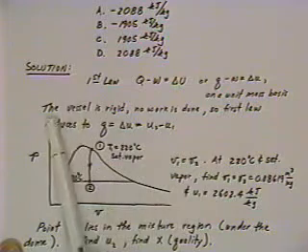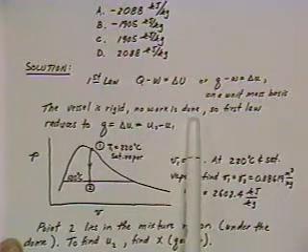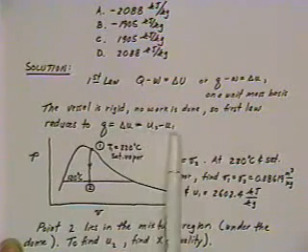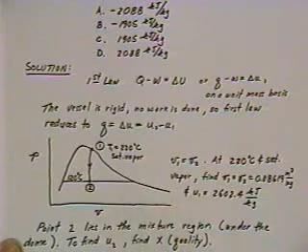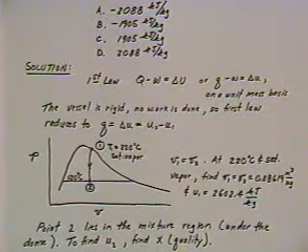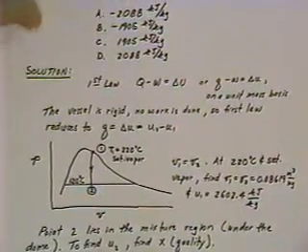Now, we also know that this is a rigid vessel. There's no change in volume, so no work is done. So the first law is Q is equal to delta U is equal to U2 minus U1. So we can now go to the saturated table conditions.